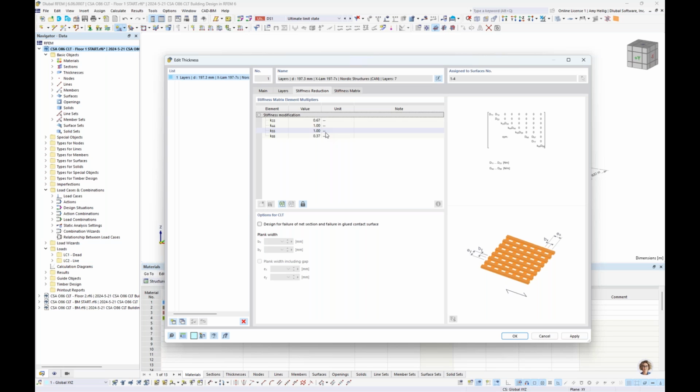Well, RFEM is actually utilizing what we call the laminate theory, and it's going to directly calculate the shear stiffness matrix entries D44 and D55, considering both shear and bending deformation. So the laminate theory is certainly a more detailed and exact approach when we compare it to the analytical equations from the shear analogy method. But point being that that reduction is all taking place under the hood with the laminate theory calculations, so we likely are not going to adjust these factors.